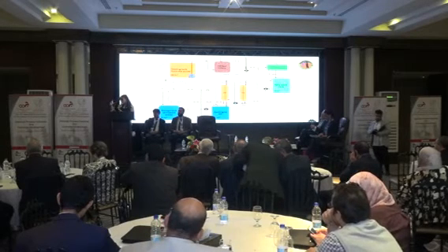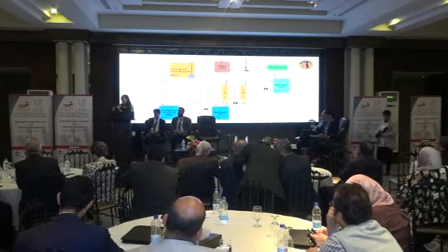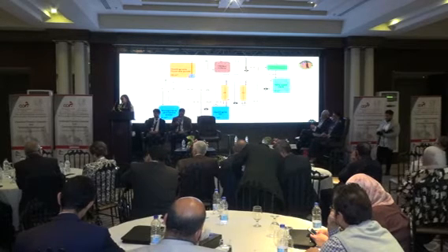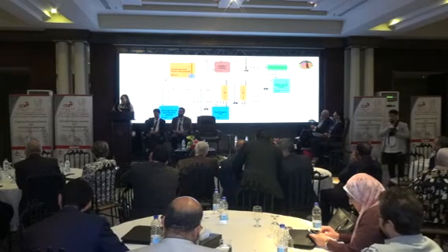But as I said, if you don't want to discharge this water into the seawater, and you want the zero discharge loop, you can use this low TDS water for any further facility in your production facilities. That's why I decreased the TDS concentration to 5,000. It can either be discharged to the seawater, or be further treated and used in other production facilities that you have.